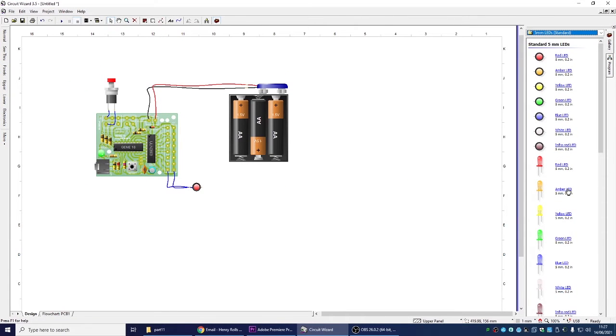So yeah, red on output 0, amber on output 1. Remember the flat side on the right, when you drag it you can see it. So flat side to Q1, and then the common one is positive. Now that to me is a bit unintuitive. You would have thought the positive gets spat out of the program and puts on an on. It's often called logic 1 is on, and you think on is going to be volts, but actually what's happening here is it's draining. So this is the high, and it's opening, almost flushing through into 0 volts here. So it's opening this gate, the transistor, and it's flowing down.